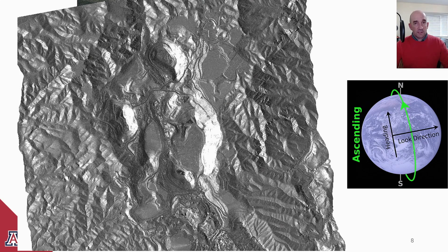Slopes that face the sensor are very bright, and slopes facing away are darker. Intuitively, one might assume that brighter is better, but recall why satellites don't look straight down. Too many echoes return at similar times, and information gets mixed up. This is true also of these slopes. They return a lot of simultaneous signal, but most of it is useless.